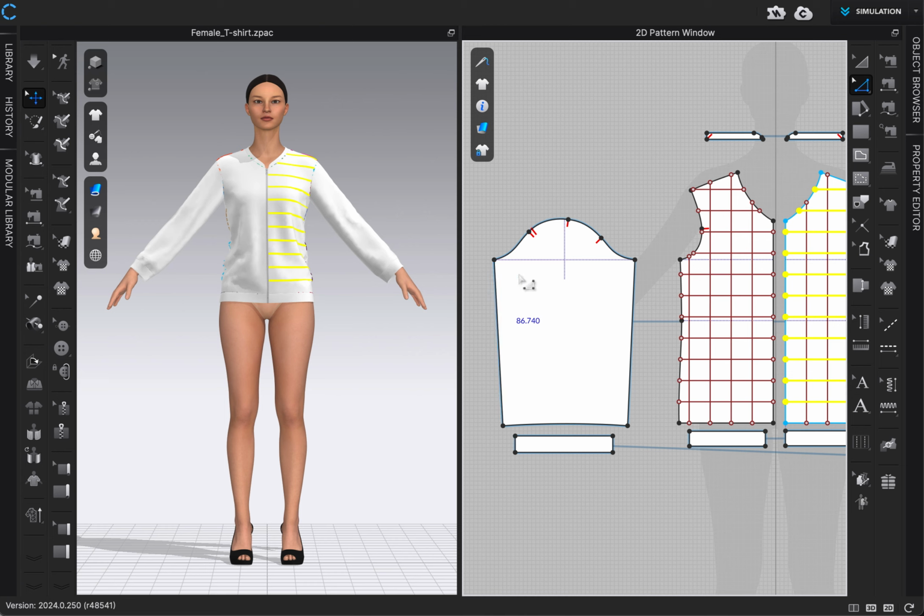But for this one, because I don't have a straight vertical or horizontal edge of my pattern, it wouldn't be as clean, or I wouldn't get the look that I'm going after if I offset based on the pattern edge, because that would offset these lines at that angle. So what I'm going to do is first create that straight vertical and horizontal internal line for myself by using the internal line tool right here in our 2D toolbar.